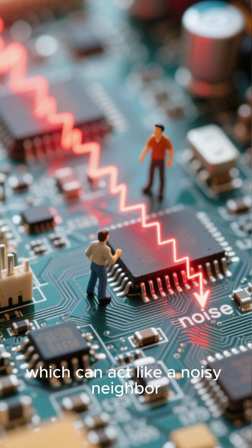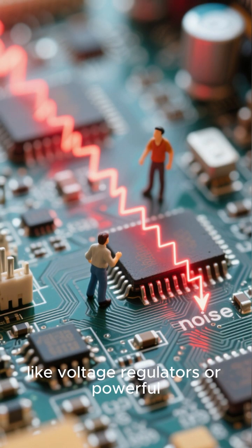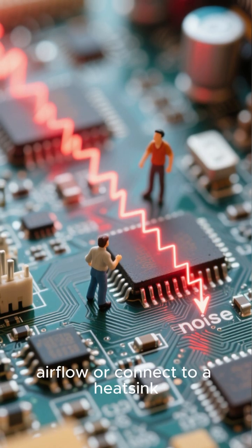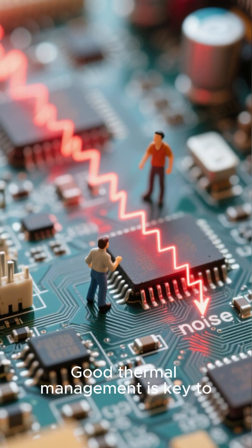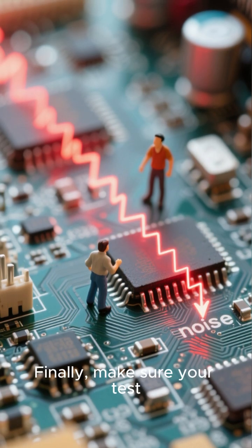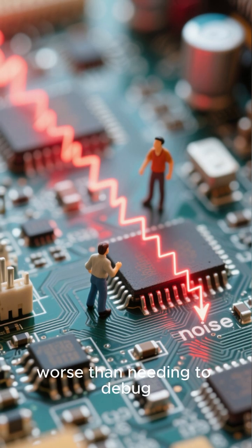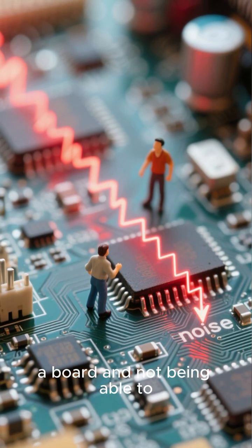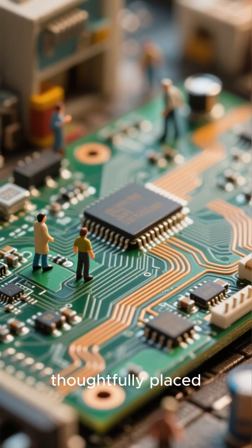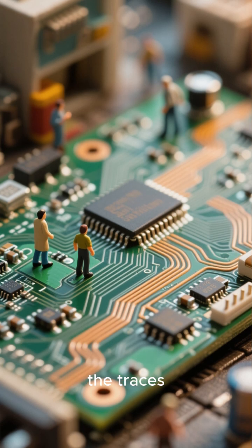noisy neighbor. And don't forget about heat. Place components that get hot, like voltage regulators or powerful processors, where they can get good airflow or connect to a heatsink. Good thermal management is key to reliability. Finally, make sure your test points and critical components are accessible. There's nothing worse than needing to debug a board and not being able to reach the point you need to probe. Once your components are thoughtfully placed, we can start talking about the connections themselves, the traces.